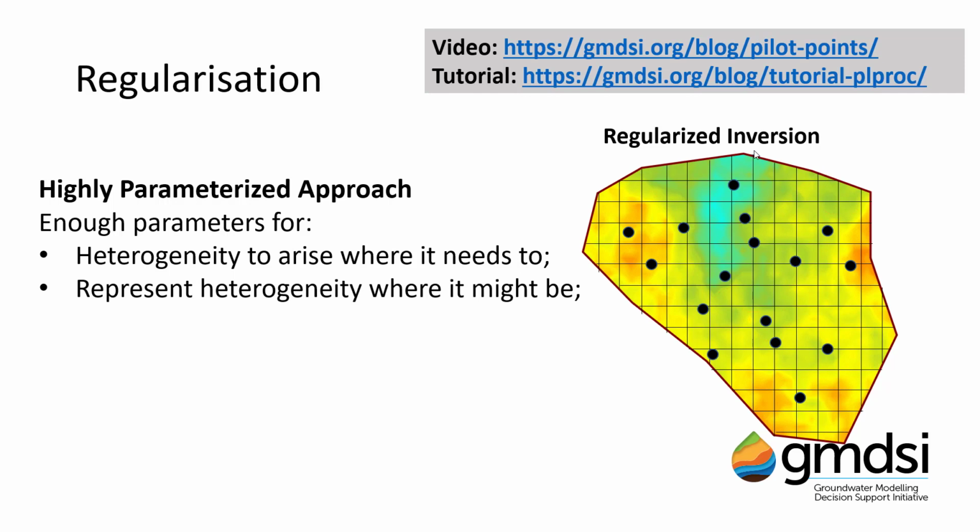Regardless of the parameterization device that we use, to undertake calibration we still need to identify combinations of parameters which are uniquely estimable given the data we have, and we need a mechanism through which to express expert knowledge to those combinations which are not uniquely estimable, for which we use singular value decomposition and Tikhonov regularization respectively.